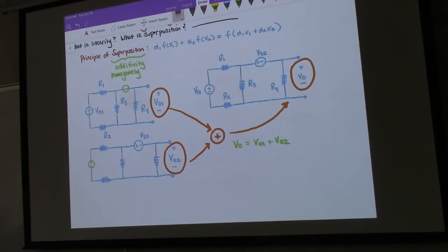But when we're trying to find this Thevenin and Norton equivalent, we'll see it helps us because we are trying to isolate out two different characteristics, which is R Thevenin, RS I called it, and V Thevenin, and we want to calculate them individually. So the ability to take the sources out of the equation for a second, then calculate R Thevenin, then do the other one separately. Essentially, we'll see when we get to the method, superposition is the basis upon which the method relies.